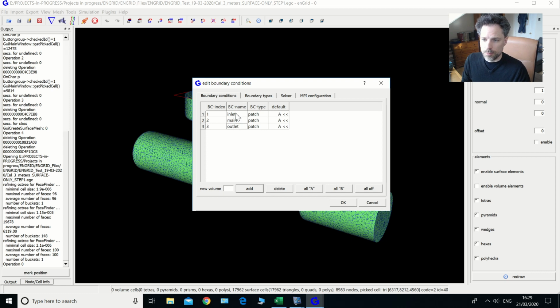These can be anything you want, but bear in mind these are going to be what you need to put into OpenFOAM, the case setup. So if you're doing this yourself to use in my tutorial case files, if you use different names here, it won't work because the OpenFOAM case structure's got these names plugged into it. So make sure you've got continuity there.